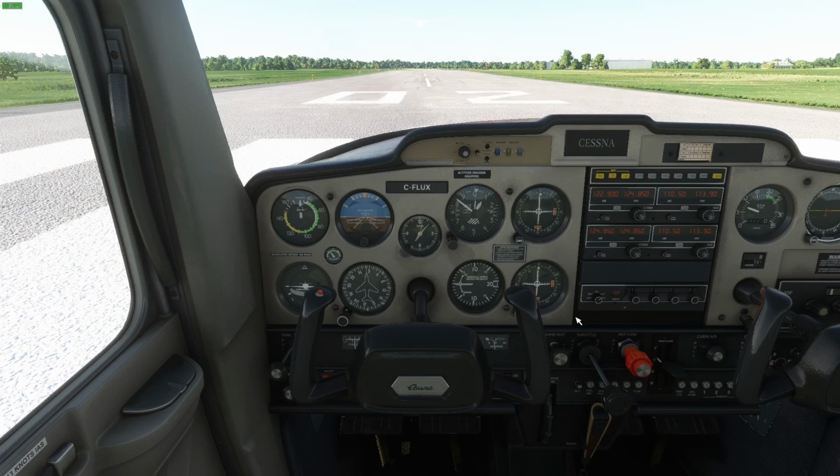Then we're going to turn left again, descending at 500 feet a minute from 1,000 feet above the ground to 500 feet above the ground, where we'll turn left, pointing straight at the runway, descending the remaining 500 and doing a landing. So that's a circuit. We do it as square as we can.